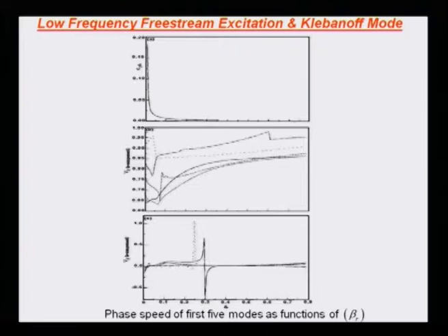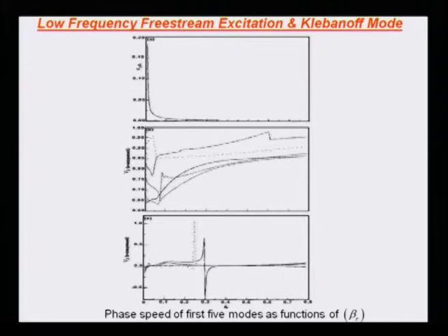Maybe somebody should cross check them again and probably obtain them with much higher accuracy, but this is what we obtained, that these are all downstream propagating modes, right. But the phase is very close to 0, that is what we saw in the top frame. The velocity with which it goes is roughly in the 2/3 to U infinity range, right.